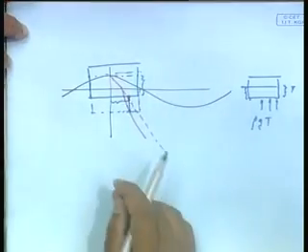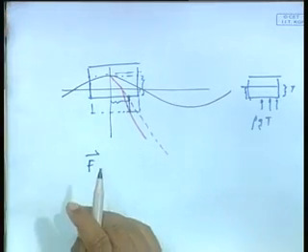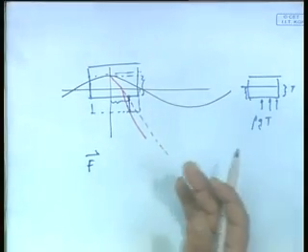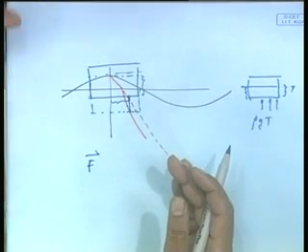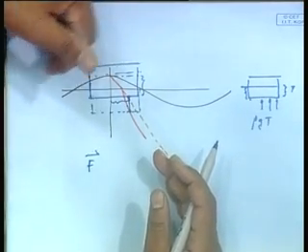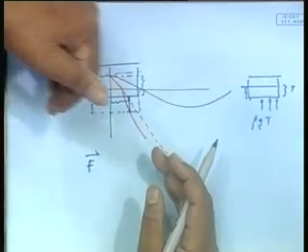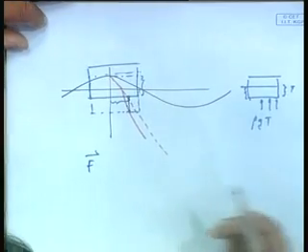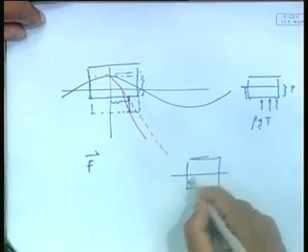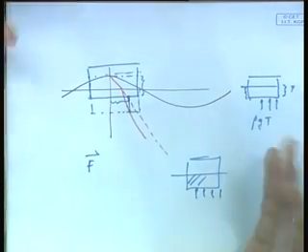Now why are we interested in dynamic pressure so much more? Now let us look at this in the same case also, hydrostatic balance case. Ultimately I want to find force. For any dynamic system I would like to find out the force, the net force acting on the body, because the entire module C keeping is because to study what the waves do to the structure. What does it do? Well, in a hydrostatic case, if there is a body there, it gives you hydrostatic pressure, that gives you buoyancy, and that is what keeps it afloat. Everything is based on that.